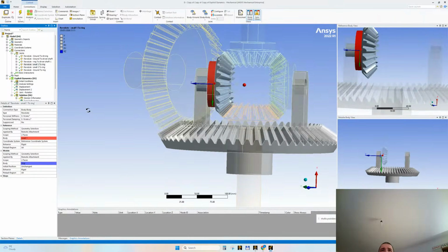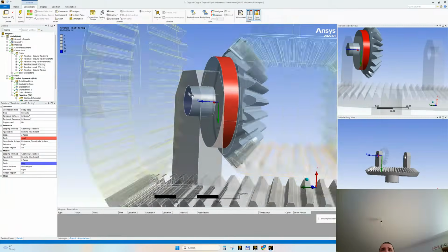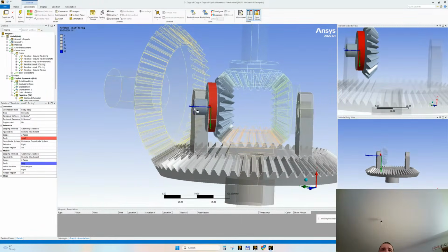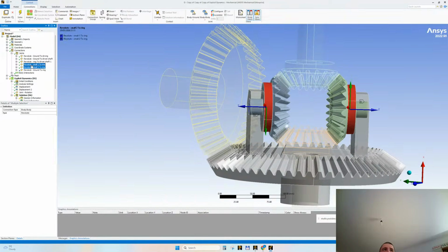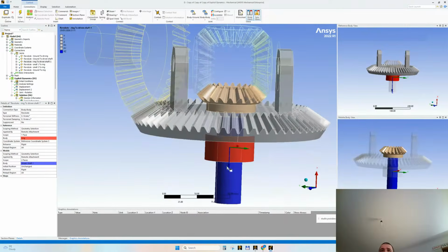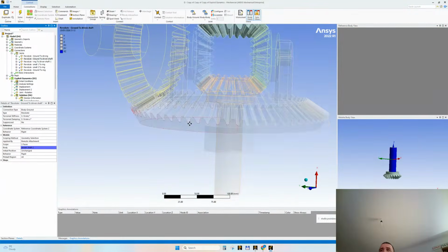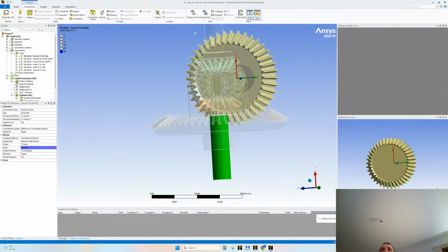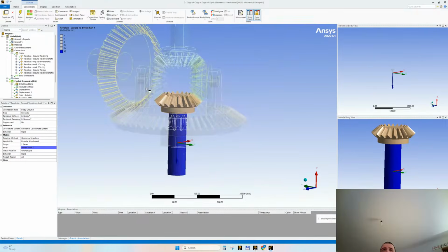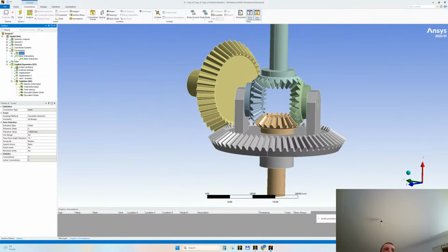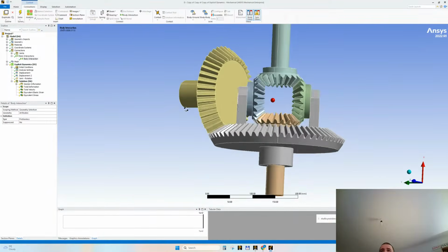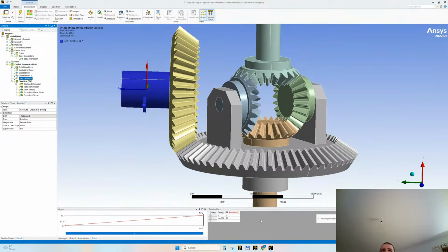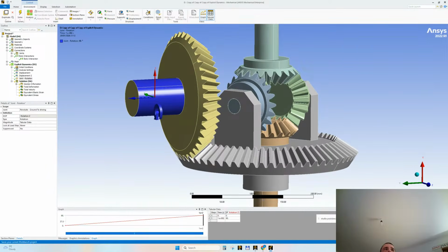But 1 second. Because we have a gap, why do we need to have this? We have proper contact here. So let's suppress this. Here, I will also want to suppress this. I would like to keep that one, the driving, and this one. Let me assign ground, body to ground Revolute. And everything here will be made due to the so-called contact, which is present here, all bodies frictionless. Now we'll have a smoother engagement because I cut the displacement in half. Let's hope it works.